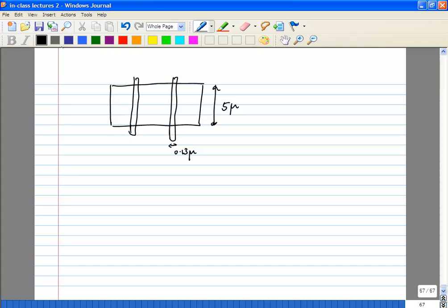And then all you have to do is, and you can do dual gate contacts also, and that's okay. So this is called a multi-fingered layout. So you can increase the number of fingers and trade off your gate resistance. In this case obviously your gate resistance is half in a coarse way.